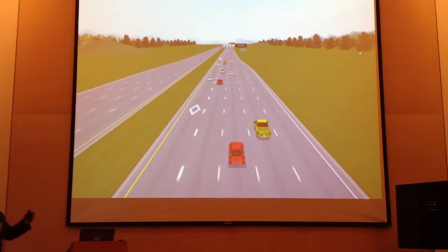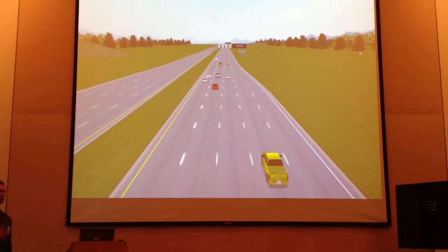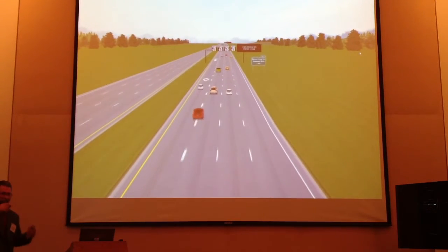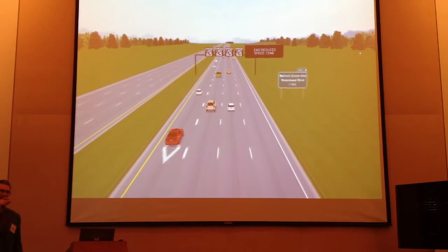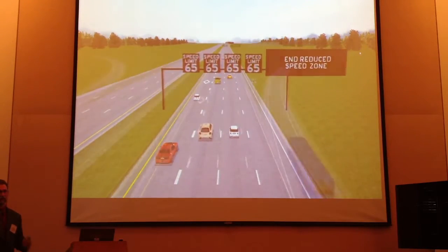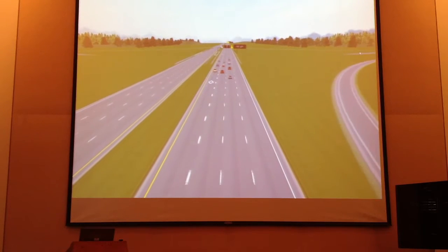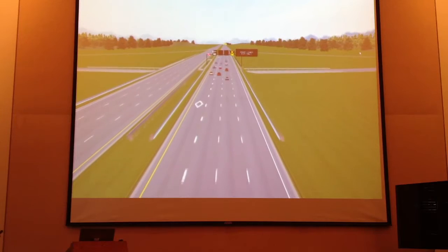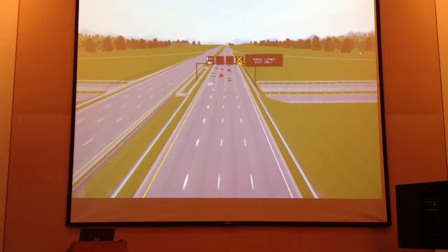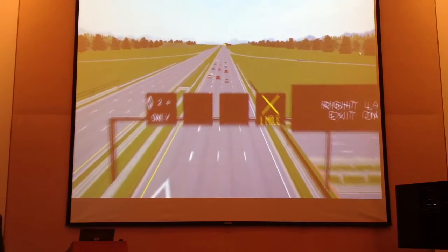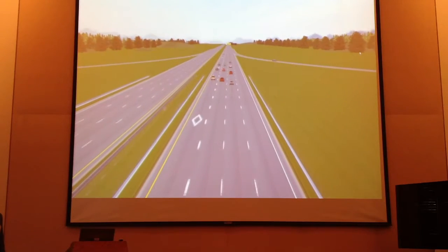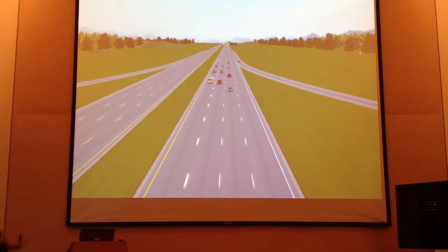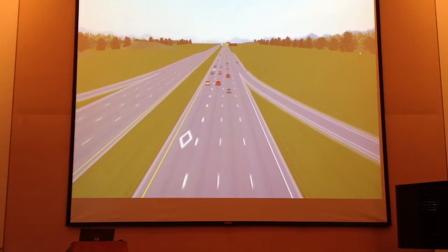And these LED-based signs are bright, at 3 to 4 times what you can see for legibility distance of regular signs of the same size, just because of how bright they are. And this is a big challenge, especially in a simulator, where what we're doing is pixels. When you're far away, you have fewer and fewer pixels representing the same thing. And usually the algorithms to figure out how bright to make the pixel blend and merge some of those sub-pixels, and you get more of a blur or a gray, where it was too white, so you don't get a solid anymore.